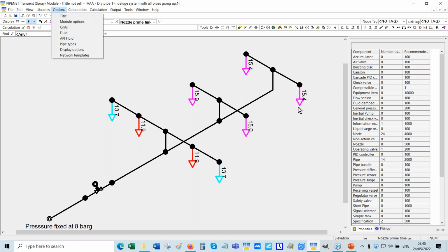By the way, why is it quicker? It's because the flow rate through the nozzles is less. See, so the flow rate through the pipes actually is quicker because these are taking less water. That's the reason why the discharge time is slightly shorter. So, when you have bigger pipes, in steady state, typically it's better because it's less friction loss. But when you're calculating the discharge time, it is not always an advantage to have big diameter pipes because they take longer to fill up.